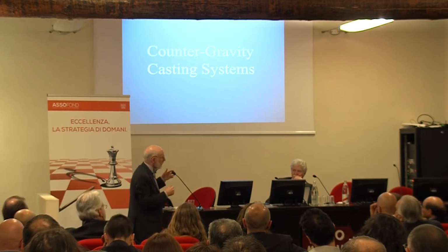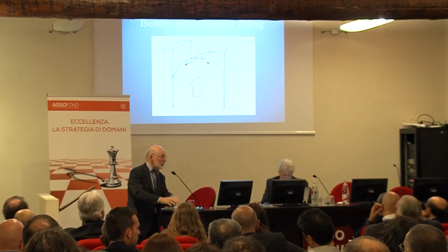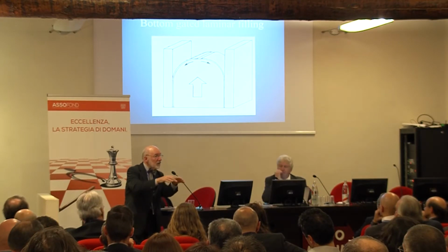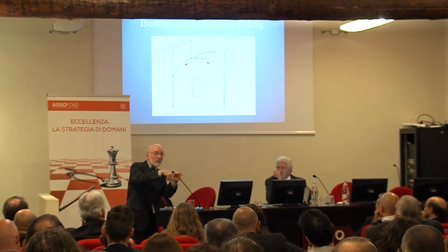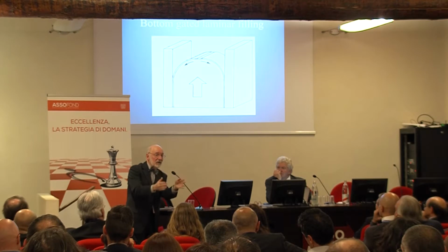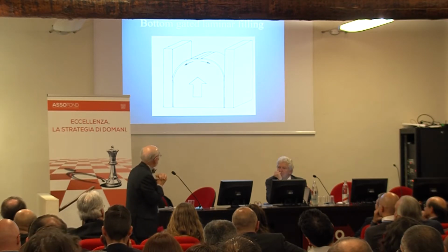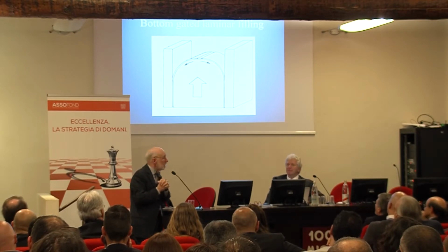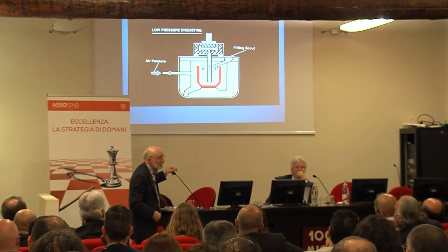So one of the big ways to get this nice filling method, whereby the metal is coming up and moving to one side, so we never get the surface oxide into the metal, is that it always becomes the skin of the casting. That is counter-gravity casting. And it really does make good products if it's done correctly. And there are plenty of ways of doing it badly. Okay, so this looks like a good idea.